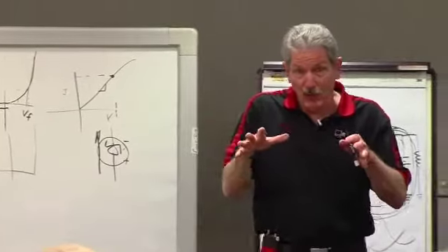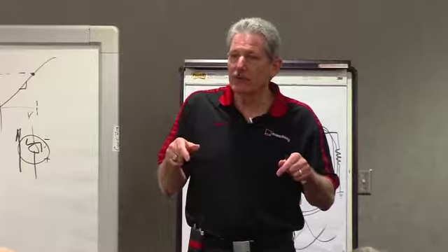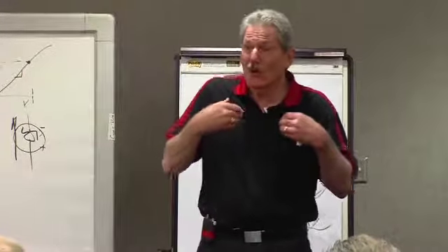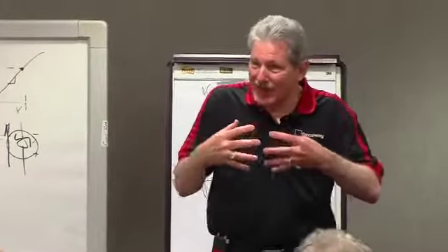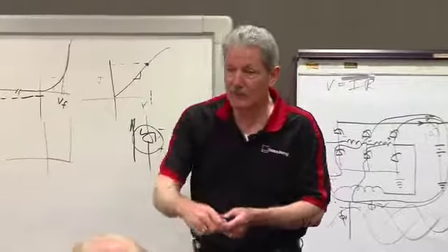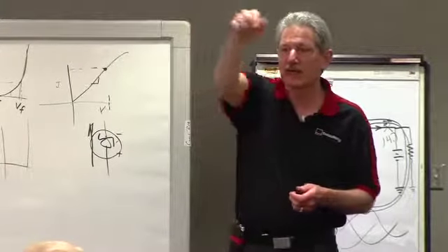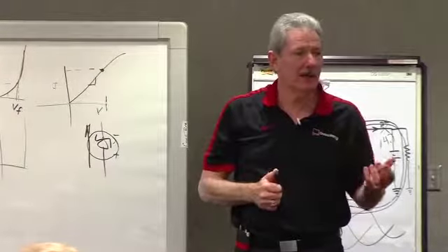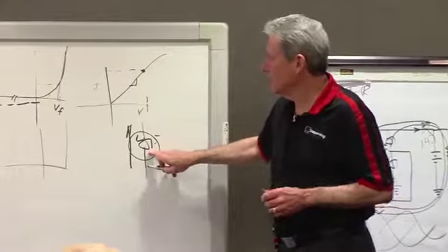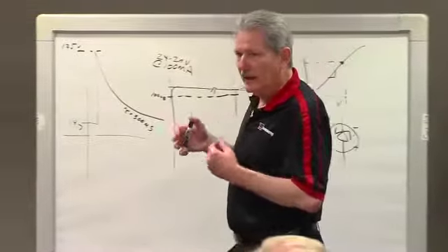So now we have, back 30 years ago, Remy sold the first centralized load dump protection alternator. We create the load dump inside. So we stopped that, and now the whole vehicle could put the money back on the table because we're protecting to 40 volts, so each of the individual electronic components doesn't have to. So that covers the Zener, the standard diode. All right, let's move into regulation.